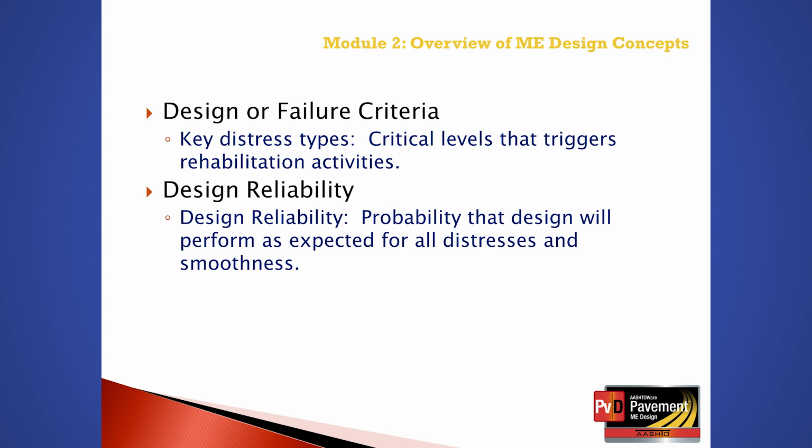The design criteria are the threshold values that trigger some type of structural rehabilitation activity that excludes pavement maintenance and preservation treatments. The design reliability is the probability the design strategy will perform as expected over the design life for all distresses and IRI predicted by the PMED software.